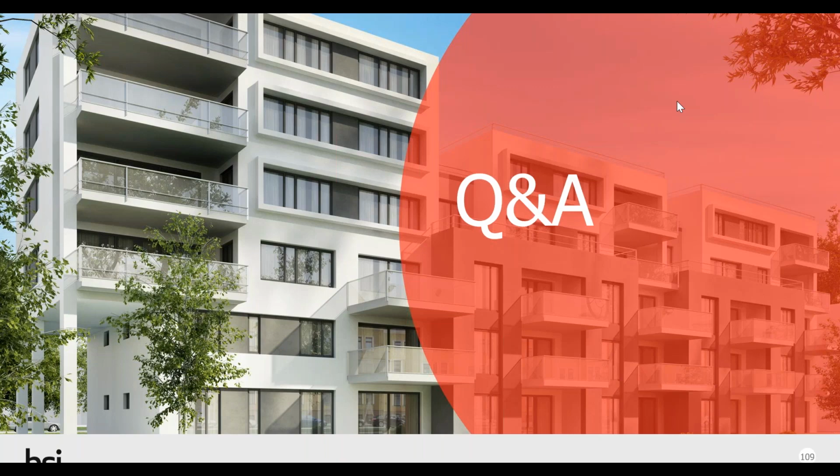The standard, of course, as Tony has highlighted, tries to remain neutral in that it does say that laminated glass could be exempt from the recommendations within the standard if an assessment of risk proves adequate resistance to the spread of fire is maintained, and also draws attention to national regulations. So I think that's basically it in terms of laminated glass.